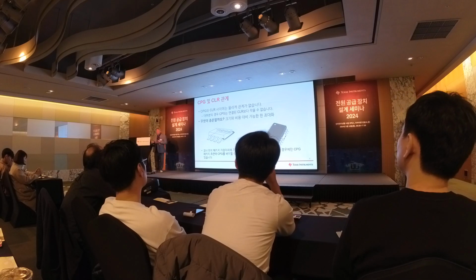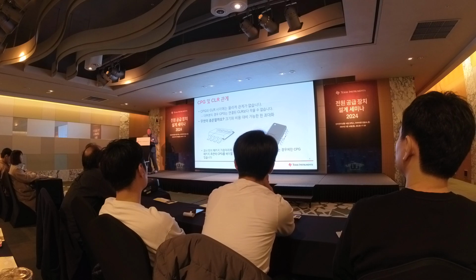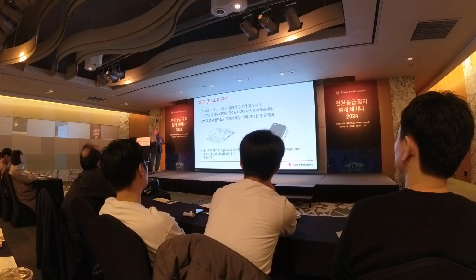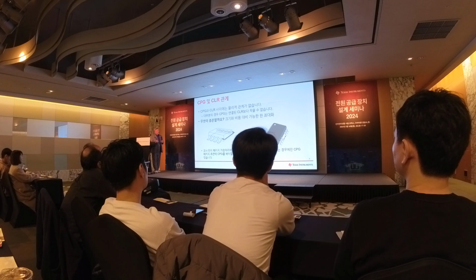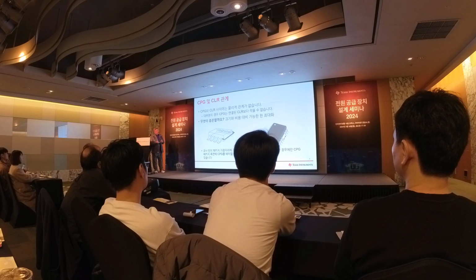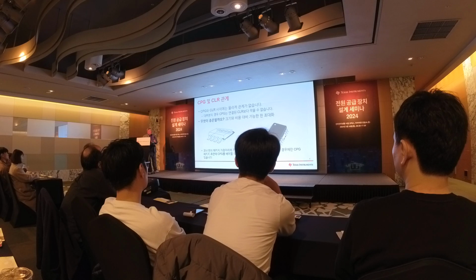Okay, so looking at creepage and clearance, there is no physical relationship between the two. And in fact, the distance between the two could be the same given the way that the spacing is working. Another key point here is that the distance is the shortest path, and that's not always over the top or under the bottom of the package.